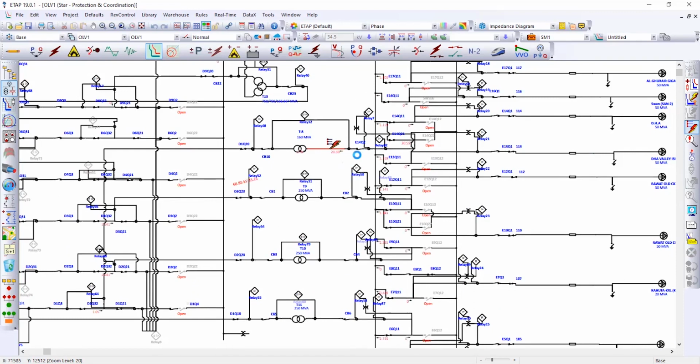Here it is visible the purpose of the reverse directional overcurrent relay, as only in the case when the fault occurs on the respective transformer circuit or transformer line, then the respective circuit breaker trips. As there is no tripping on other transformer circuits, a continuous supply to the load is ensured.